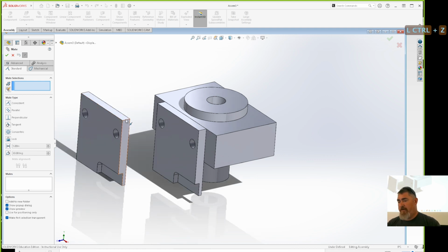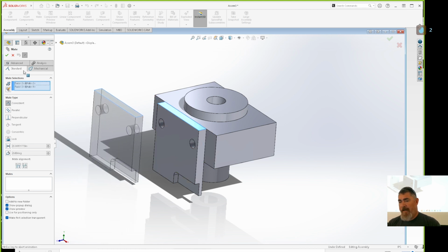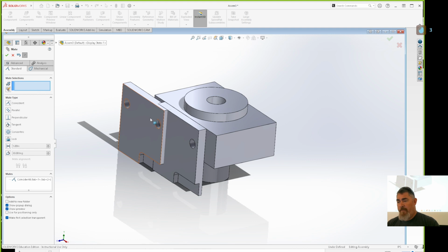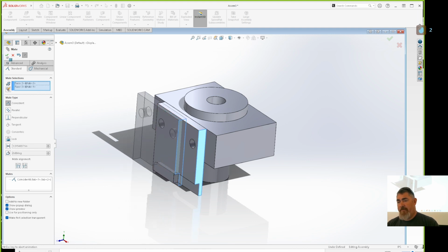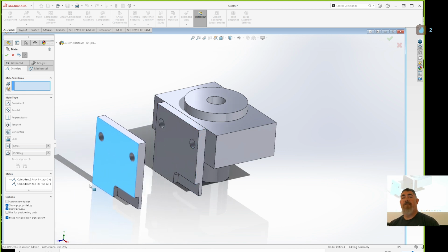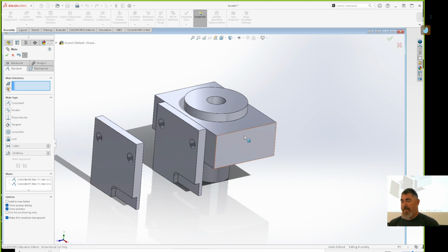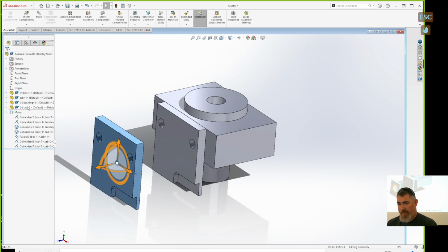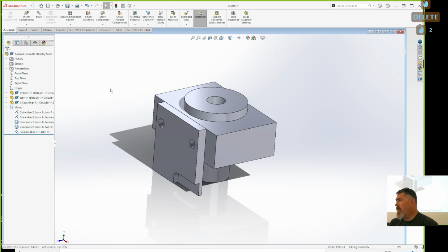Same thing as if I had picked the tops there, and then sides here. Now it's a slider joint, basically, right? I haven't controlled the distance there, but it can slide back and forth. And whether I pick the side there or if I picked just this side to be parallel with that side, right? It would allow me to slide, because I'm not giving it a set distance. So those are the mates that we have in SolidWorks.